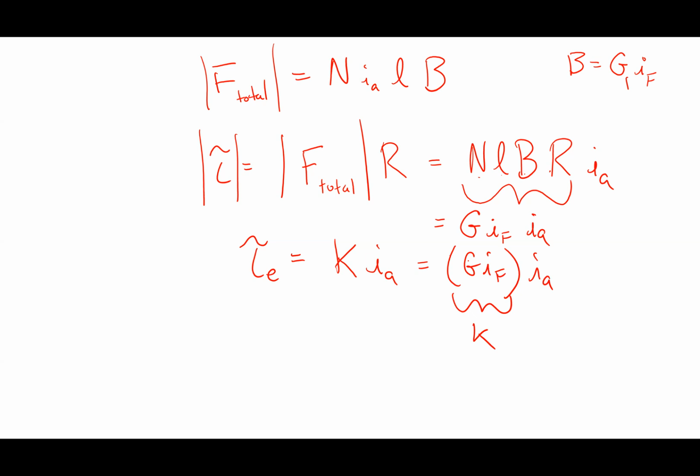Now, the other thing that's important is that ultimately I have to figure out something about the speed of the machine, right? You heard a louder noise as I increased the voltage. Why was I hearing a louder noise? Higher RPM: more voltage, more speed, more current, more torque. That's the key relationship. So more voltage, more speed. Now let's see if we can figure out why that should be the case.